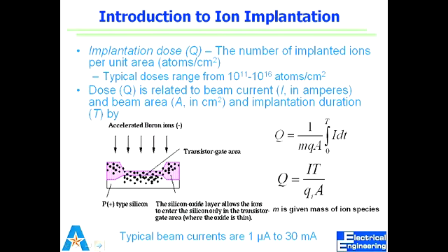So when we have the device ready for the process, we end up putting some hard mask, right? And the mask may itself have a specific thickness to it, or maybe it's just an opening. The thickness will define how deep we want the profile to go.